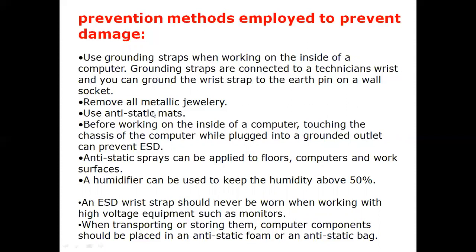Whenever you are working on internal components of the computer, if you are wearing any kind of metallic jewelry, you should remove it. Use an anti-static mat. If you are taking out an internal component, you should place that component on the anti-static mat. Before working on the inside of a computer, touching the chassis of the computer while plugged into a grounded outlet can prevent ESD.